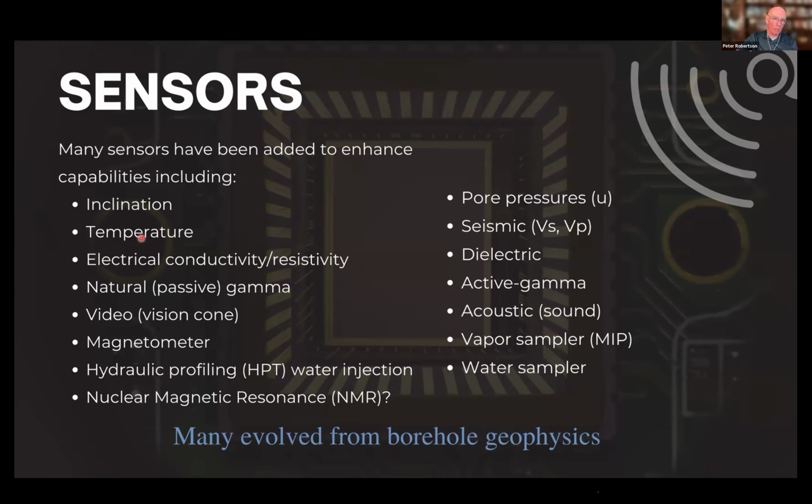And so it might be a hot day with 30 degrees air temperature, but when you push it into the ground, it drops to 10 degrees. And so that temperature shift can affect the strain gauges. But nearly all cones now have a simple temperature sensor on the strain gauge, and they're all temperature compensated. So it's now pretty standardized that they're temperature compensated.